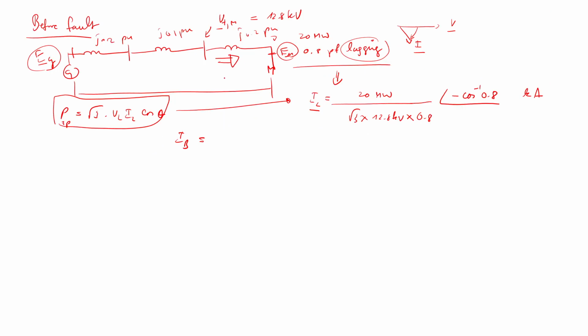The rating of the machine is what, 30 MVA, the problem says, so both of them have the same rating, 13.2 kV as a kV base. So the I base essentially is 30 MVA divided by root 3 times 13.2 kV, right? So you can change this, IB.